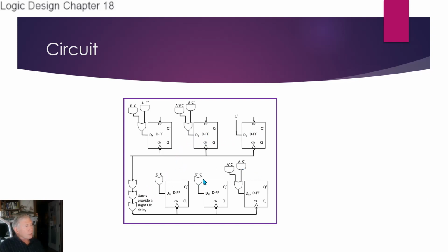These output equations, this output network, relies on these flip-flops being in the correct present state. So if we didn't put a delay in the clock line here, which I know I told you to never do, but in this case it's required, then our desired outputs are always going to be one clock cycle delayed, because when the clock hits here, the current inputs are going to be our old state, not the new state that we're going to. That won't happen until the propagation delay expires.